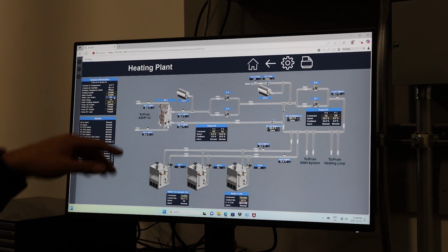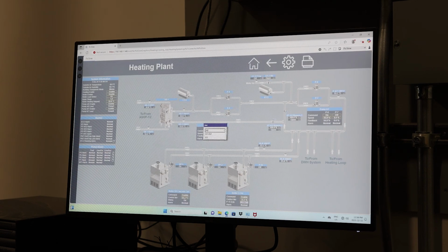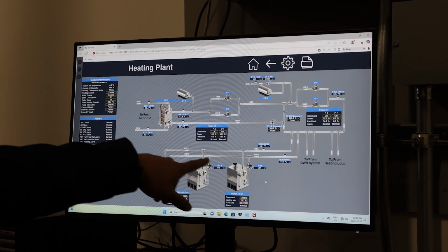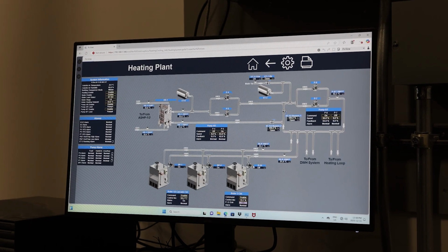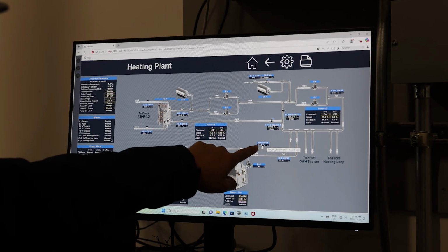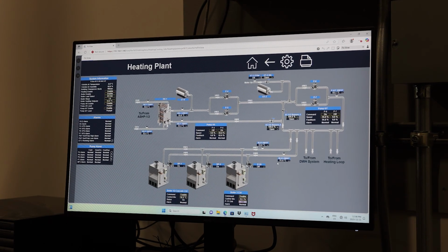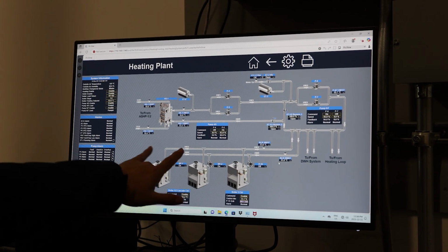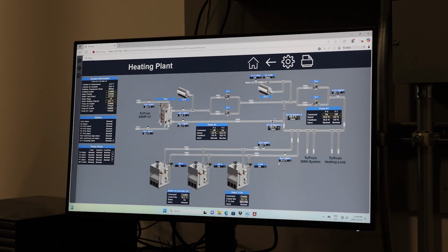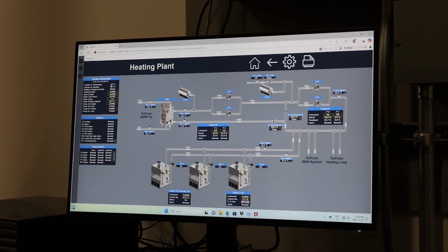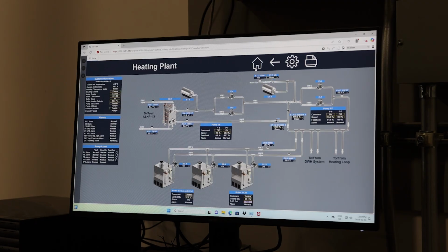Yeah, but right now I want boiler 1 and boiler 2 to be running because I need to work on this VFD a little bit. The boiler supply temperature, boiler return temperature, they are on the common line, not the individual boilers. Outside temperature is here. It's -8. That's for the ERV.